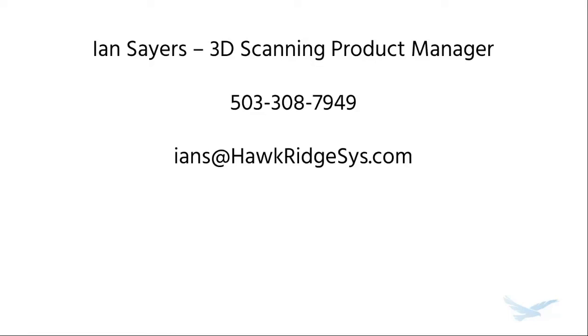Yeah, and to further clarify, there are X-ray and micro CT solutions on the market for industrial use. One of our good friends and customers, Delphi Precision Imaging in Redmond, Washington, has a big industrial CT scanner, and they use Geomagic Design X to reverse engineer files from it. Reverse engineering data from one of those X-ray or CT systems is exactly like any other line-of-sight scanner, any garden variety scanner. The approach is the same. You just have more data, and you have the internal data without having to cut something apart.